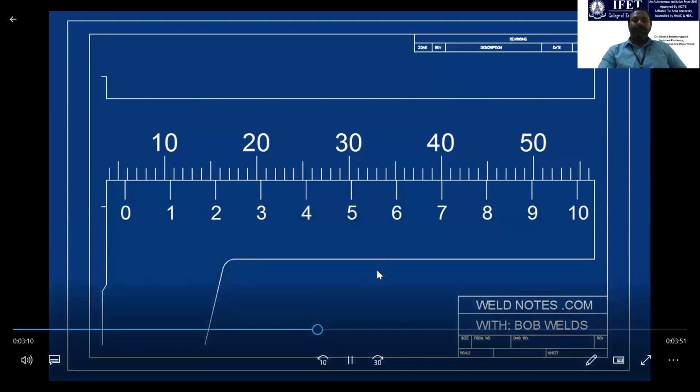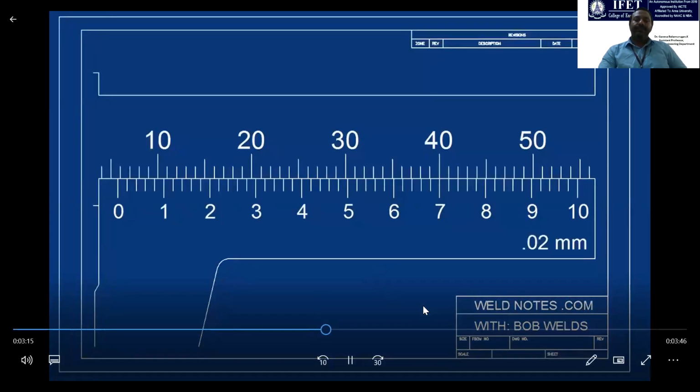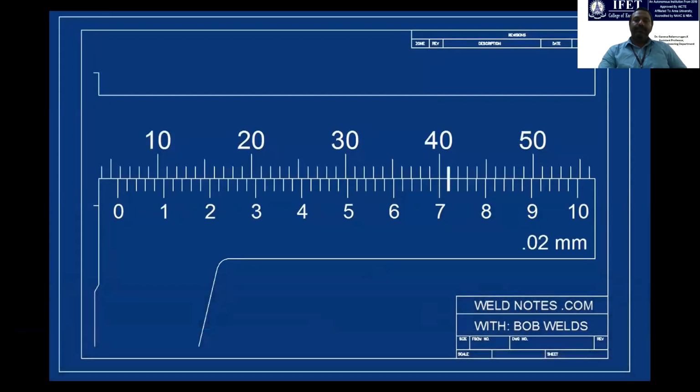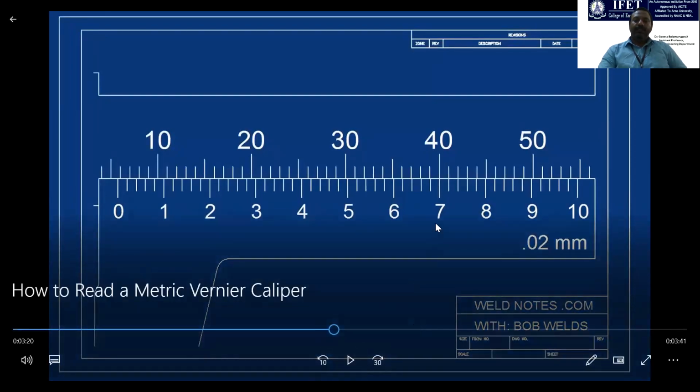Millimeters. But this caliper can measure even more accurately than that. I'll redraw all the marks and let you look again. Now, see that the mark next to the 7 lines up best. Now what they are saying is that there are 5 graduations between the major graduations of the vernier scale, 0 and 1. Each graduation here, 1, 2, 3, 4, 5, is marked as 0.02 mm. This is the least count that we calculated in the previous slide.